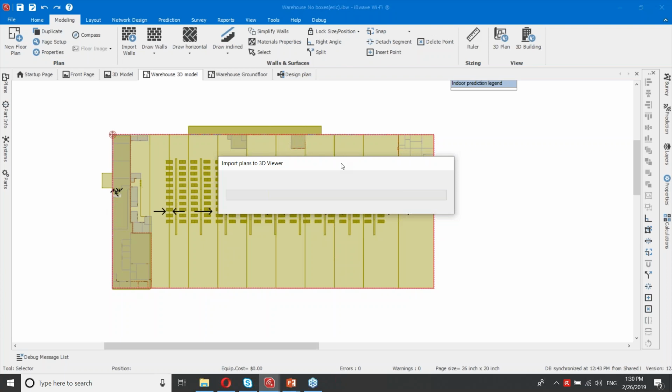Well, Dan, while we're waiting for that, just one question that came up. What are the main design criteria thresholds for IoT in indoor environments? Well, for IoT in an indoor environment, typically you would want to know what your noise level is at the plant, and you would want your signal-to-noise ratio to be at least 18 dB, which means your signal should be higher by 18 dB than the noise.